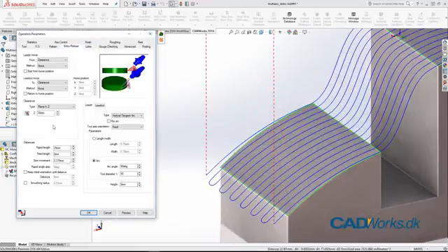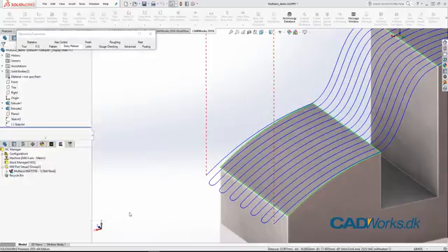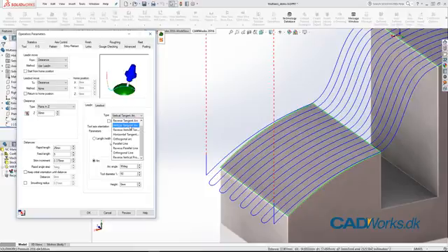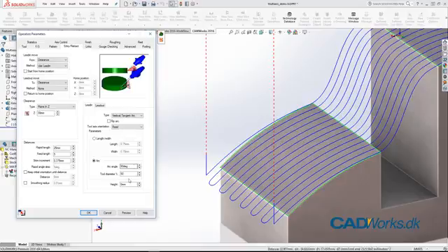So let's do some modification. I'm going to use a feed length of 5. Preview that. And then we have feed motion, and that comes in pretty sharp. So I'm going to use a lead in and a lead out motion. So let's do that. The lead in move is going to be use lead in, and then we can define in here the lead in, and in this case that would be a vertical tangent arc, and then we can do an arc angle, tool diameter, and a height for the lead in itself.